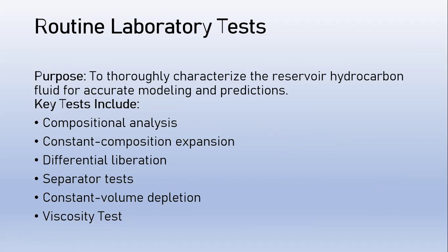For gas samples, we do composition analysis, constant composition expansion tests, separator tests, but we do constant volume depletion, while for oil, we do the differential liberation experiment, not CVD, and viscosity test for all. So 5 for each.